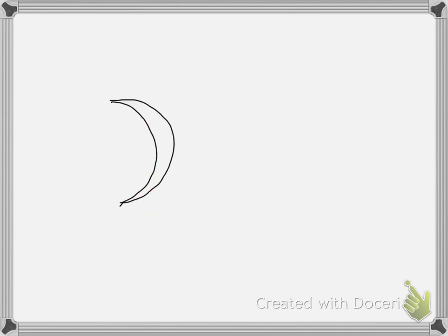So this is the guide blade of the Kaplan turbine. The water flows laterally into the guide vanes, gets deflected by them, and flows axially through the propeller. Because it is an axial flow reaction turbine, the water is entering laterally. So I am drawing this, and let V1 be the velocity of the jet of water. We denote suffix 1 as the inlet and suffix 2 as the outlet. V1 is the velocity of the jet.